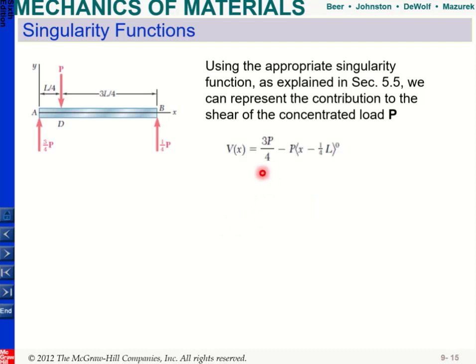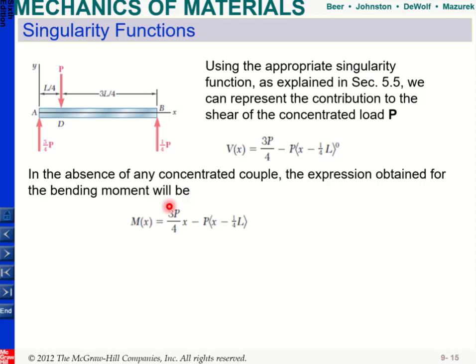By using singularity functions, I can write my shear force as given here. Let's assume that we apply a P at L over 4, and these are the supports. So this is going up when x is equal to 0, and I apply a load when x is equal to L over 4. That's why I use this expression, because it will be equal to 0 when x is less than L over 4. Then if you integrate it, and since I don't apply any moment, I can just write my moment by this equation.